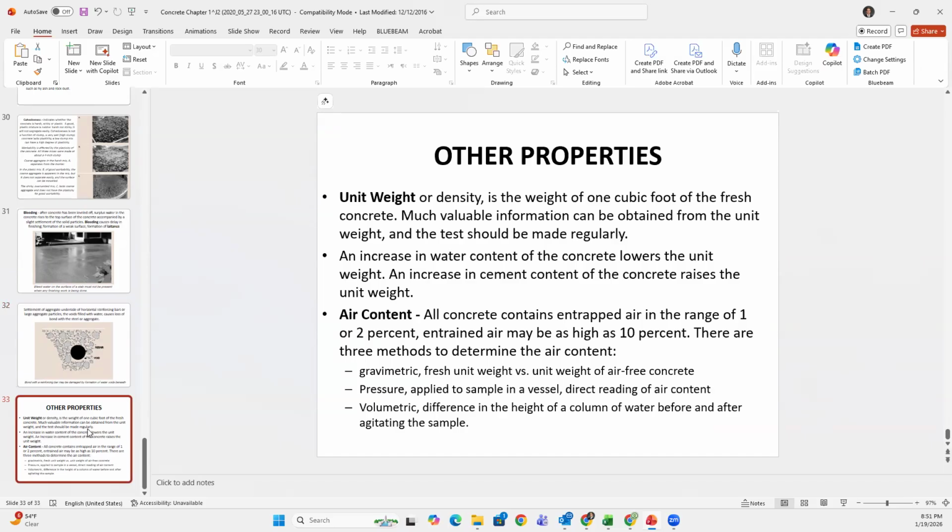Other elements that we will talk about this semester, and I briefly touched upon tonight, was the weight of concrete. By now you know 150 pounds per cubic foot, 110 pounds per cubic foot, the differences. The unit weight of concrete is determined based on the unit weight of its aggregates. So utilization of the right aggregates gives you the proper unit weight.